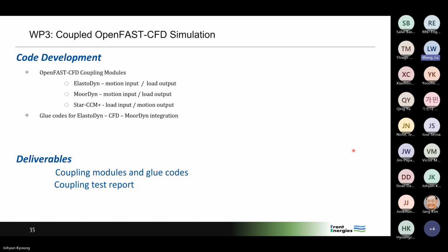The second motivation comes from the fact that certain highly nonlinear hydrodynamic loads are very difficult to estimate in mid-fidelity tools, such as wave impact loads from breaking waves and slamming loads. Definitely some progress is being made on the mid-fidelity side to predict this type of load, but I think CFD still has a very important role, both in providing validation for mid-fidelity models, but also in directly predicting the critical extreme loads on the structure.